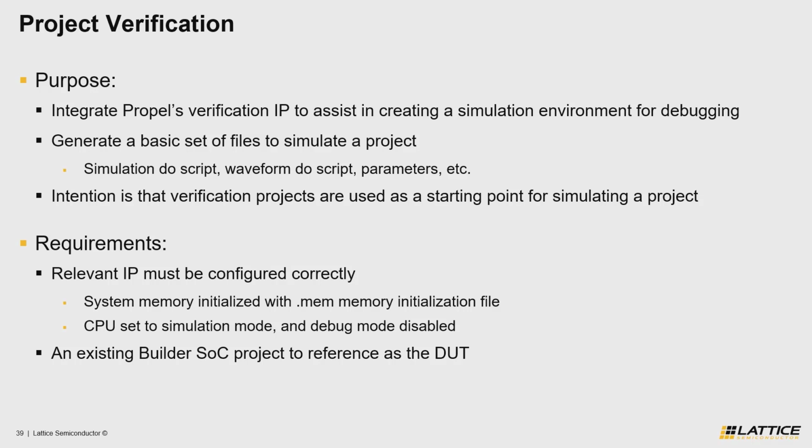Aside from that, you must also have an existing SoC project created ahead of time before you can create your own verification project. Luckily, each Propel Builder SoC project has a corresponding verification project that is generated along with it during project creation, meaning that we do not need to create our own separate verification projects and can instead use the verification to design icon in Propel's toolbar in order to easily alternate between the two projects. With that said, let's move on to the next section, so we can check out the main files that are generated with each verification project in a little more depth.